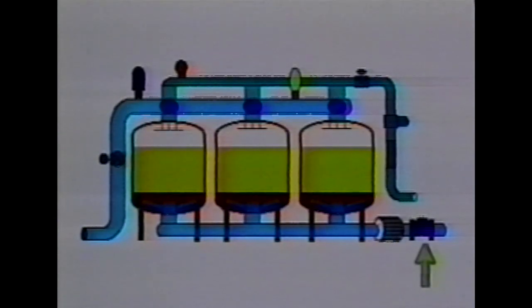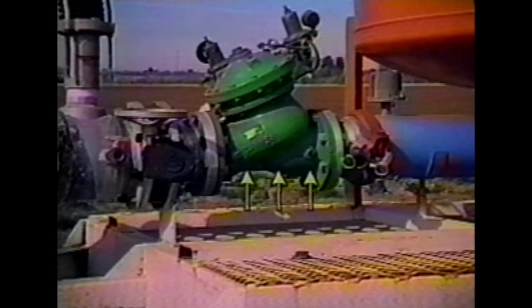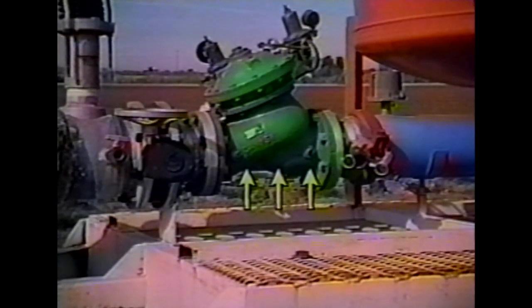A pressure sustaining valve is required on many systems. It is needed when the water supply cannot meet the flow rate to the system and to the filter during a backflush process. That scenario was discussed earlier in this video when it was suggested that 2 tank systems not be used. However, if a pressure sustaining valve is needed, one of the new low pressure loss designs should be selected.